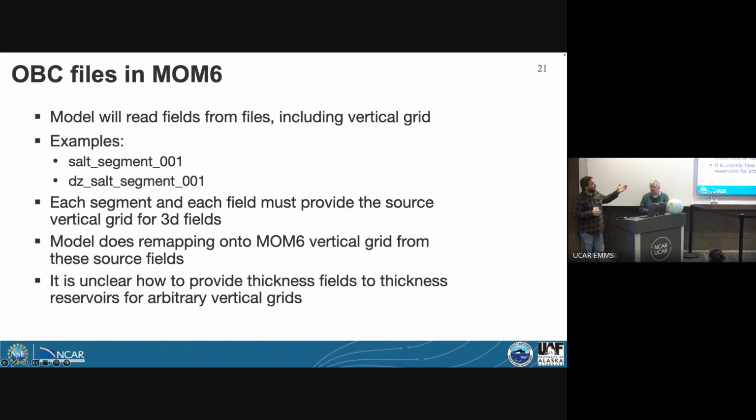Same thing with the baroclinic condition. That's why we use nudging, and we don't directly prescribe what is coming in, because then it will create instability and a lot of issues with reflection, etc. So we need to prescribe something, but you don't want to be too aggressive, and the nudging is a way to do that. The reservoir is likewise a way to prescribe stuff without oversubscribing the problem.